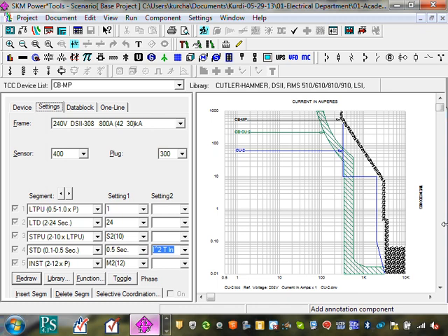So here's a long time LTPU. How many of you guys set adjustable circuit breakers? They give you a screwdriver, and you go to the face of the circuit breaker, where there are a couple of dials, and you dial them up. As you dial them up, be careful, because you are basically creating a newly designed circuit breaker. One dial will say LTPU. This stands for long time pickup. That's your overload. This one is set at 1 right now.